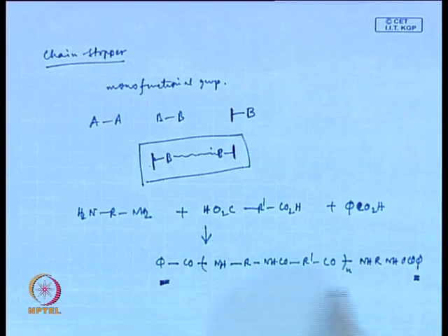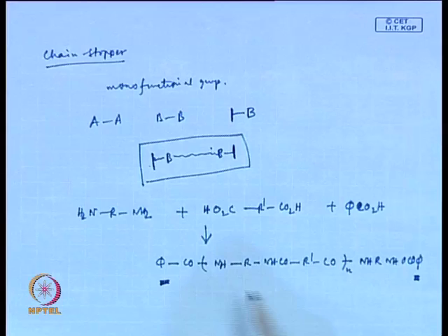So, if you take this polymer out and do further molding and compounding, because these chains are capped with a non-reactive group, they will not take part in the reaction, which means your polymers are practically dead polymers. So, your molecular weight will not change. At the end of your processing steps, you will get the same polymer, with the property related to your target molecular weight.